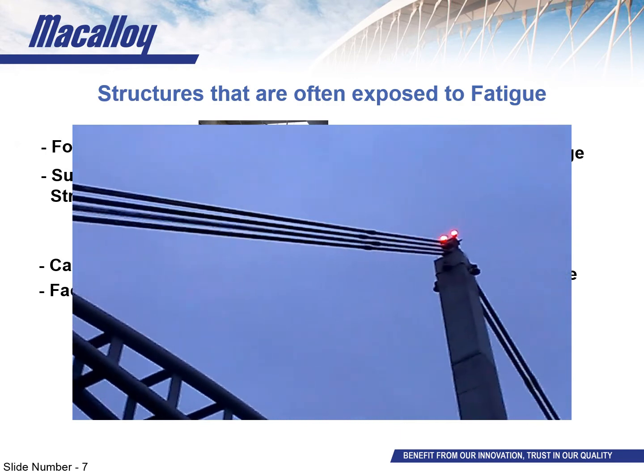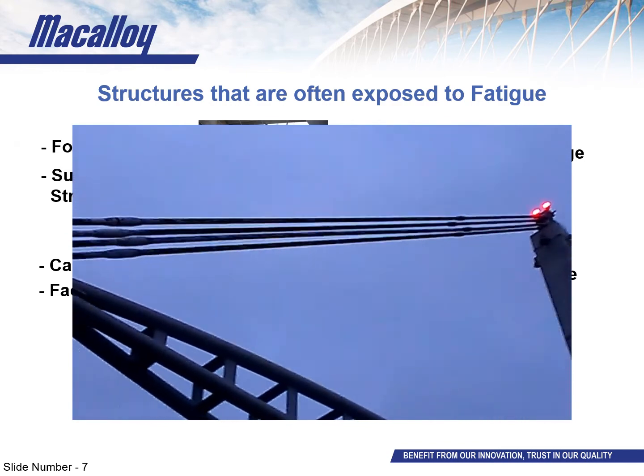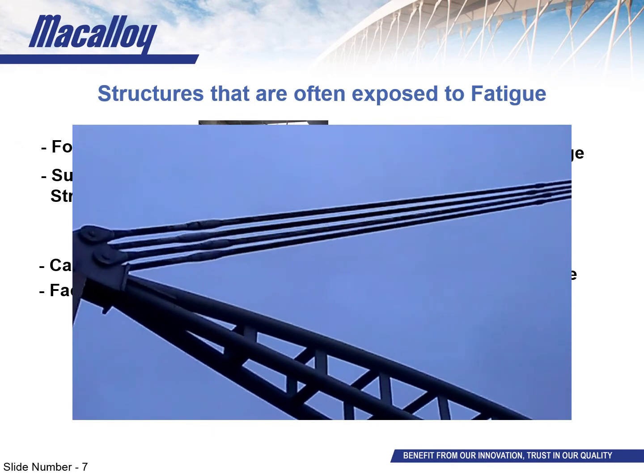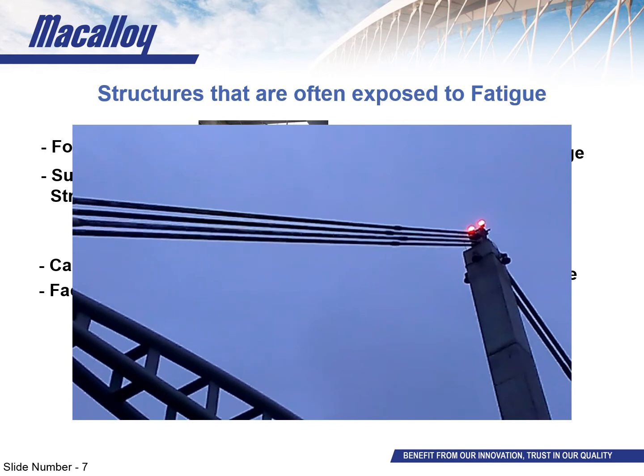Note how the bar is creating a waveform similar to that of a sound or maybe even a sine wave. The problem was identified though, and dampers were designed into the surrounding structure, as well as the preloading being corrected to alter its frequency and avoid that resonance occurring again.